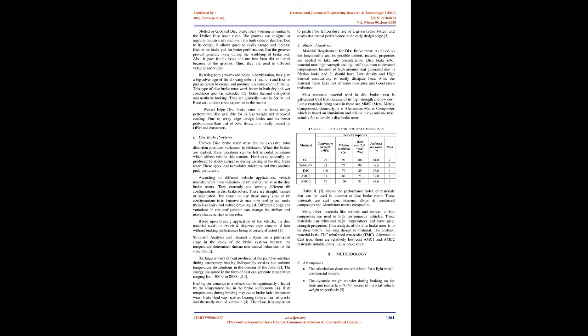Flat disc brakes, blank and smooth, have a large surface area which is in contact with the brake pad and give excellent braking ability. But after prolonged braking periods, they will lose their efficiency. Gases and heat generated and also the particles of friction pad material can accumulate between the disc and brake pad, which will cause brake fading and thus warping of the disc if the heat produced reaches critical levels. It is used for typical driving conditions and is not expensive for manufacturing and machining.